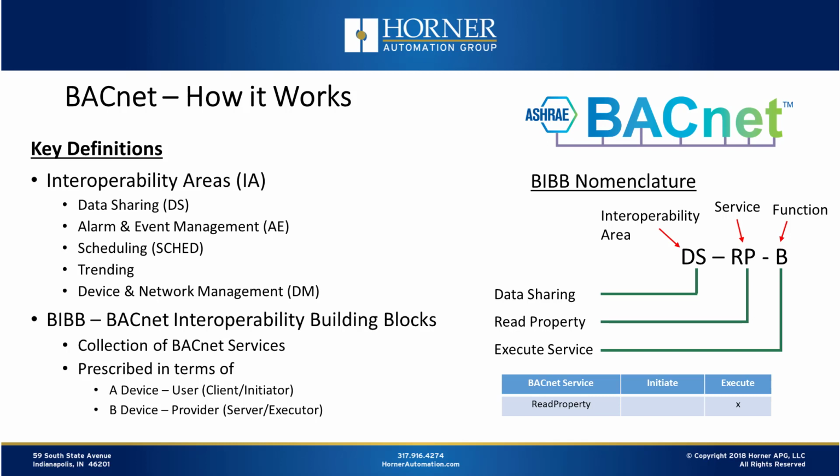You can see on the right a nomenclature that's used for BACnet interoperability building blocks, or BIBs for short. They combine abbreviations for the interoperability area, the services, and then how that is supported by the particular device as either a client, often called an initiator, or a server, sometimes called an executor. So again, these are various definitions that really help ensure that BACnet devices can share data.